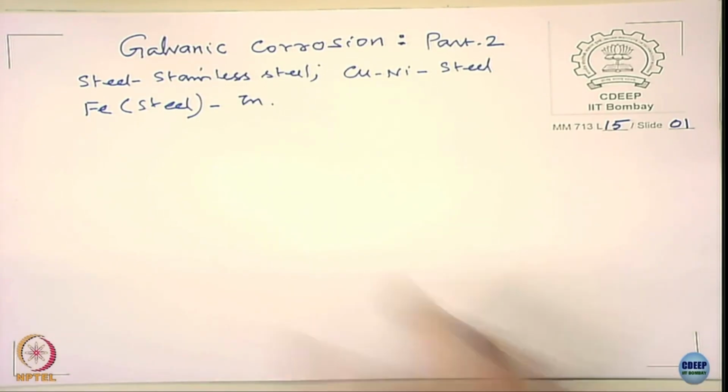In practice, it is not the situation here. You have a galvanized coating, but I don't think zinc is used as a structural material. There may be some zinc die castings, but otherwise structurally zinc is not used as a good material of construction. I took zinc for one important reason: to show that i_corr is not important in galvanic corrosion.